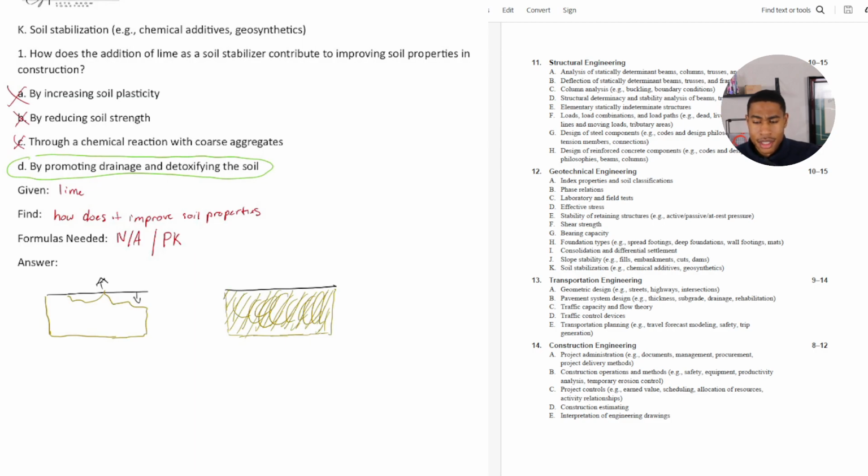When I dealt with lime, I typically dealt with it out in the field where concrete was being poured. And if I was testing the concrete and its specifications, like for a slump test, you're testing how liquidy it is. And so for some of those tests, you would have this thing called a slump cone. And when concrete goes in there, it's not going to stay clean, right? So typically, concrete forms, you're rinsing it out in the field after you've done your test, but you want to get that concrete off of your slump cone